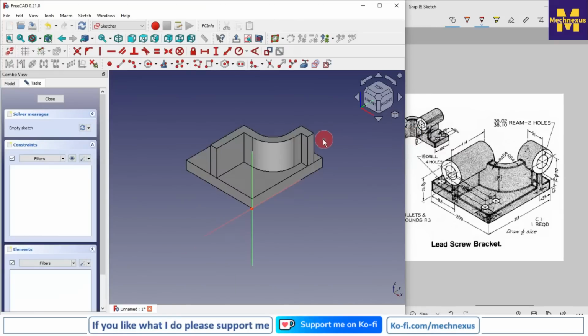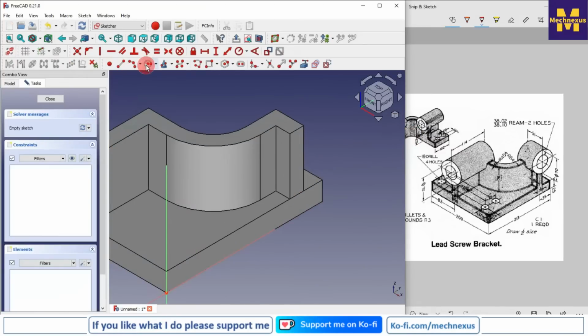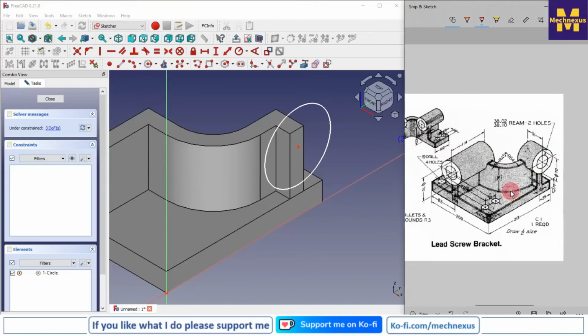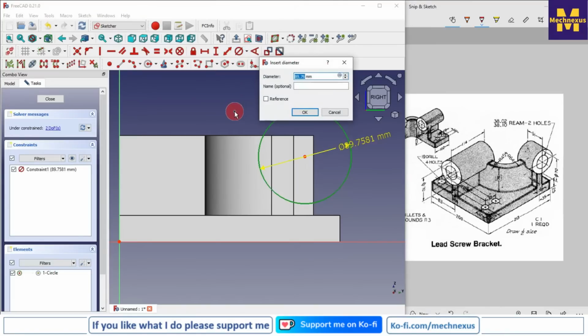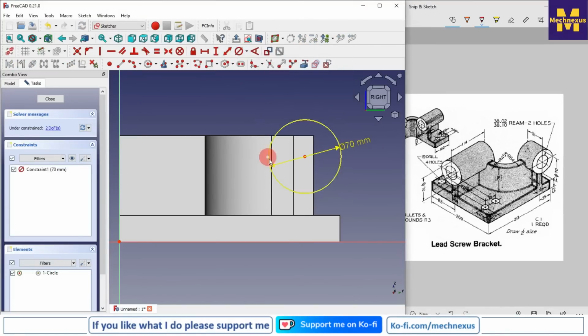I will prefer to the isometric view, and now I will create a circle on this face of diameter. It is a given 70. Now I will select this and give the diameter dimension of 70.